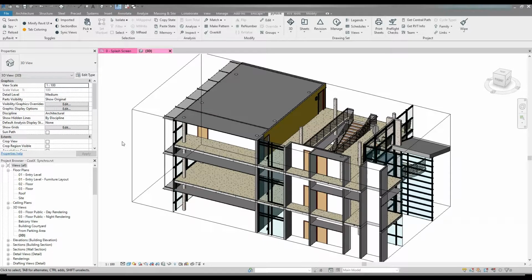In this video, I'm gonna show what features of PyRevit I use most of the time. Normally, before sharing our MEP models with architects, structural engineers, or any other parties, we need to clean the models. We need to remove any Revit links, CAD links, etc. We need to delete the views and sheets, and also we need to purge the models.